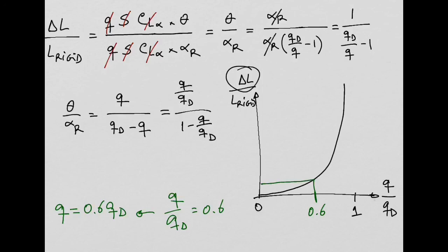So it means, due to aeroelastic effects, you will get more lift in your wing because of the deformation of the wing. So the closer you are to your divergent velocity when you're flying, more and more lift you will get. And that can be very dangerous. Yeah. So the ideal is to be flying as far away as possible from your divergent speed.